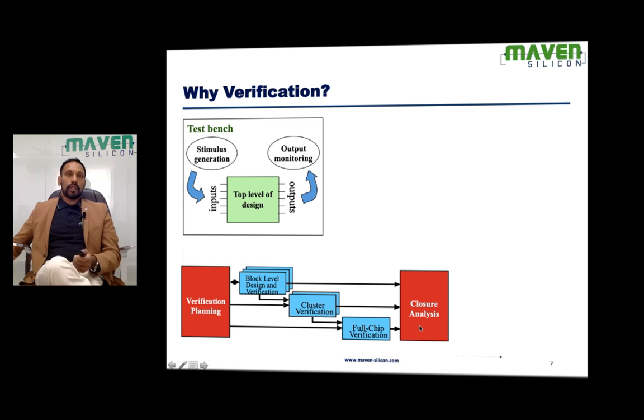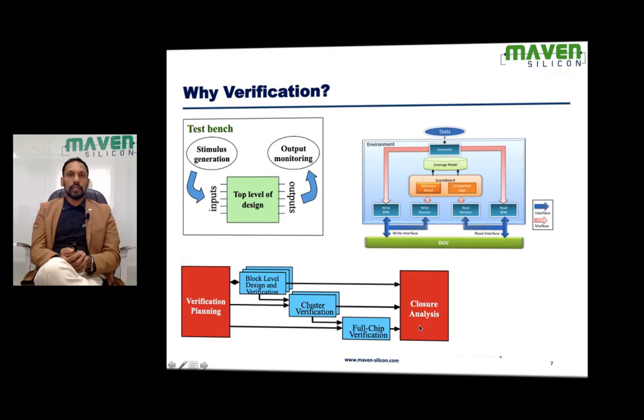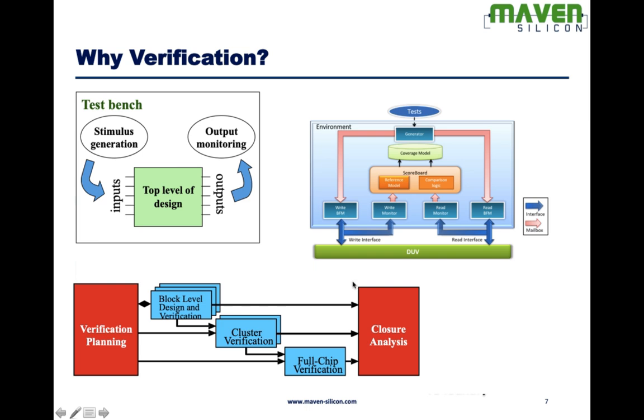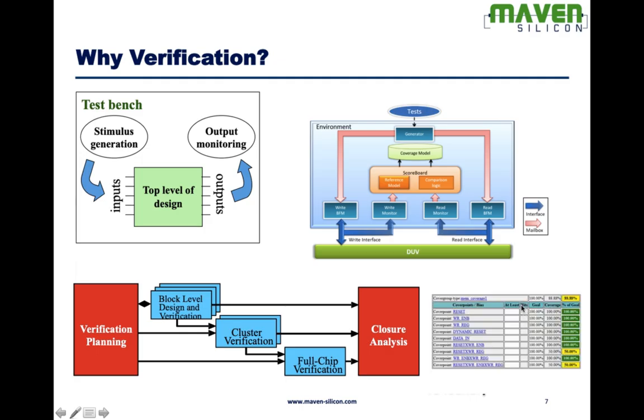In addition to the verification process, you also need to understand the test bench architecture, which is very critical. If you really want to implement a reusable test bench, we need to think how we can use the test bench across different projects or across different levels of the design, like from IP to subsystem, subsystem to system level verification. So that's where the architecture becomes critical. And you also need to understand how to deal with coverage information and sign off the verification.